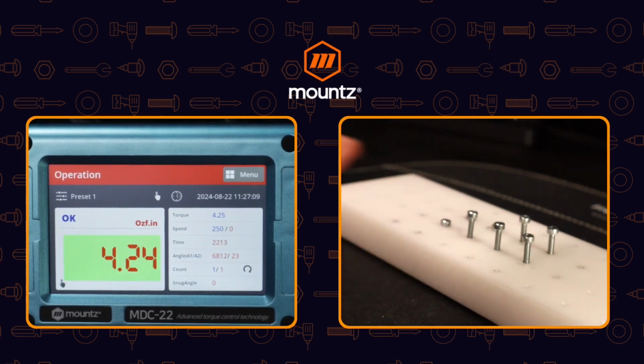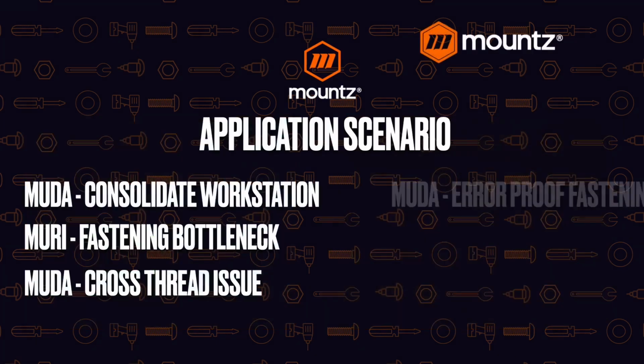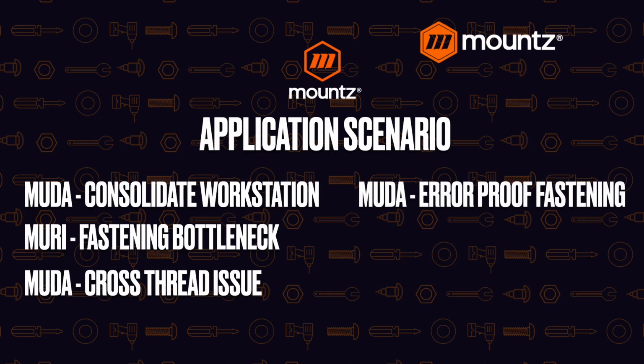So that can help with the cross-threading that you may see, giving us that ability to start the fastener in the reverse and then transition to the fastening direction. Again, we're utilizing the soft start feature with this as well to help combat both of those, or at least that one issue there.